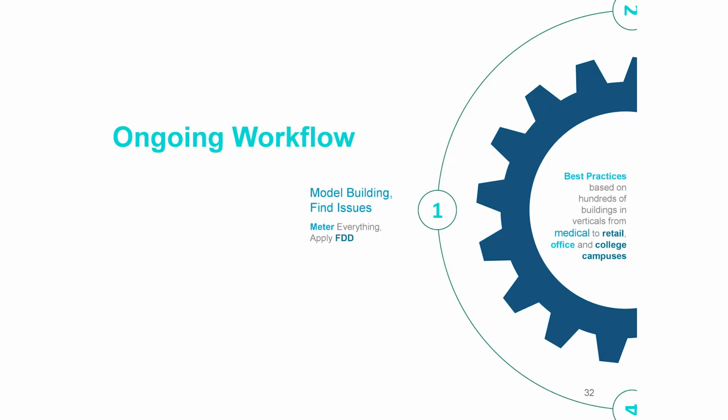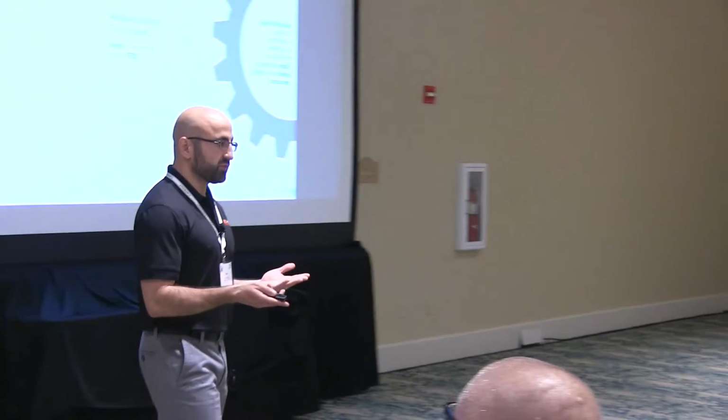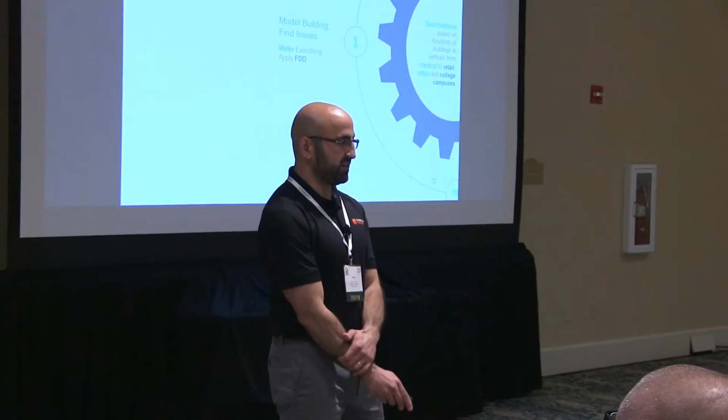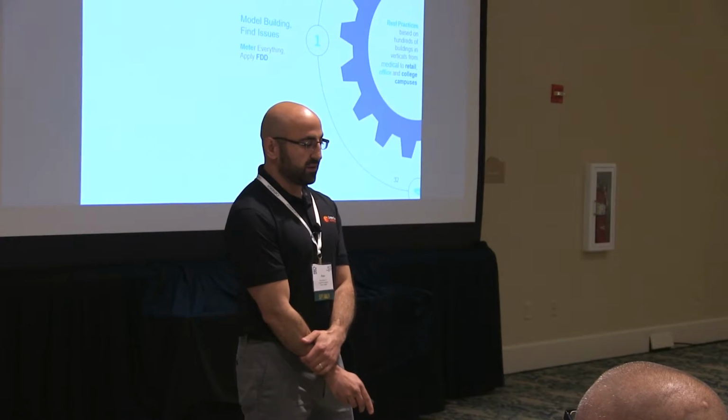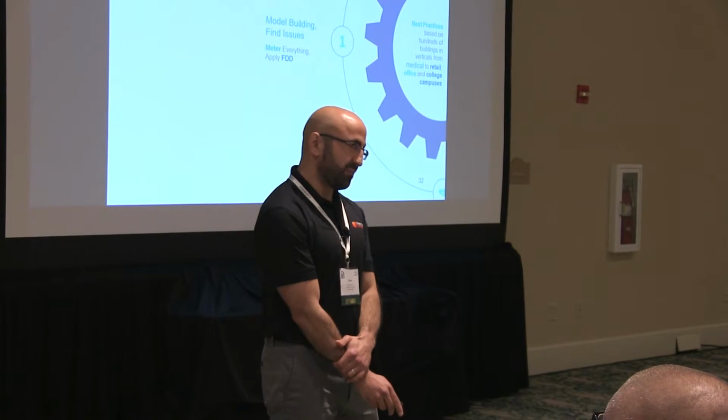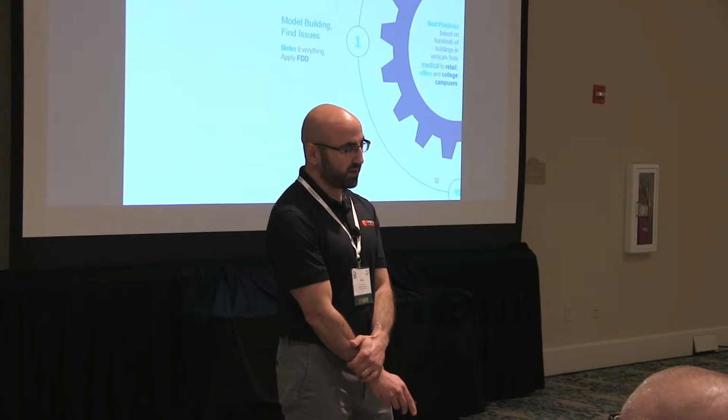and love to answer some of your questions. So virtual metering, does that qualify for some FDD protocol or specifically for the protocol moving? It does. There's a couple of utilities that we are approved for, both in US and Canada, for using virtual metering for M&V. If you look at the FEMP IPMVP standard, option B, it also qualifies using virtual metering as a method to quantify savings using that option B protocol. And also for performance programs with utilities as well.